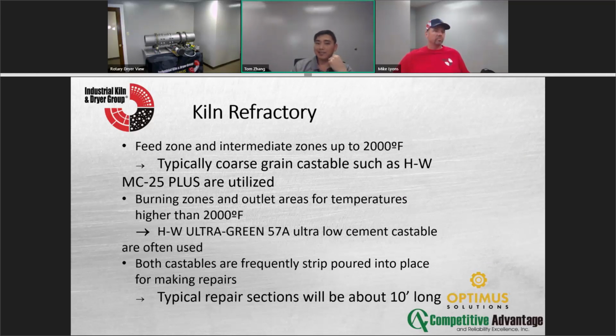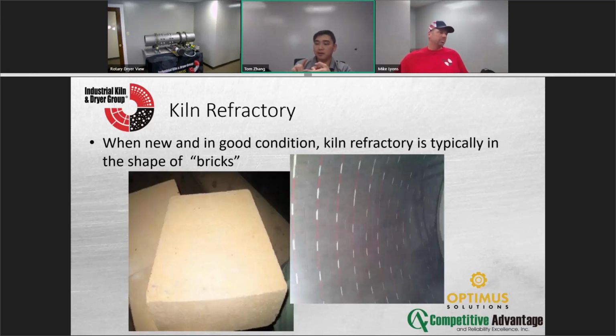You've got a lot of different refractory types. Some of them are basic, what I call a basic refractory, so your magnesiums, and then you've got your aluminas, and this is where all your refractory groups can make different recommendations based off of a chemical reaction or conductivity. So if it's good conductivity in terms of, hey, it's not so hot here, we can get away with a lighter brick. Or you change thicknesses. I mean, you've seen it, right? People change refractory thicknesses. When you do that, make sure to look at your loads.